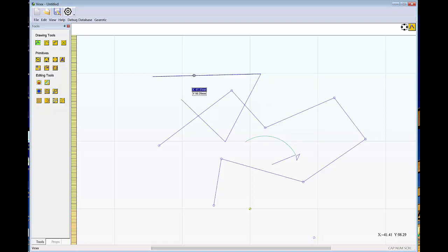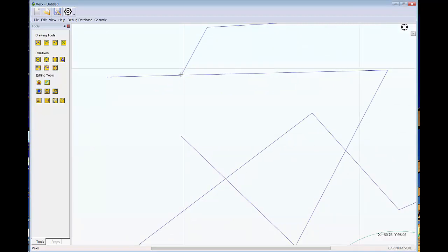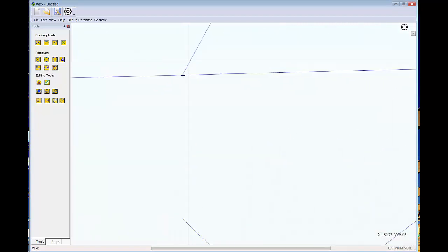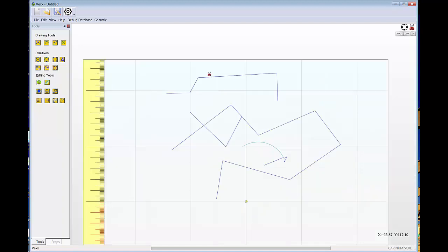So if, for example, I go to the line drawing program, hit the control key, and hover my control key over a line, I can then use that position to connect other drawing entities to, and that line will actually be part of and connected to the original contour line. It won't form its own contour. If I select it, you can see it's a contour that begins at the line, but this can make it easier when you're trimming something, because then it knows where that line connected because you actually drew the line connected to it.